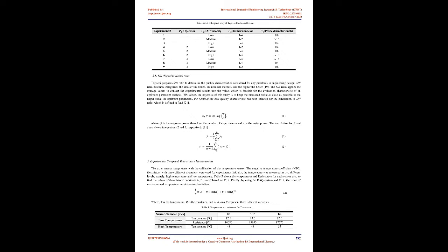It was found that process parameters such as melting temperature, packing pressure, and geometrical parameters such as gate and runner design are considered significant parameters [12 to 14]. DOE, ANOVA and TOPSIS, technique for order of preference by similarity to ideal solution, for analyzing the effect of manufacturing parameters on the final quality of injected parts were applied. The contribution of each parameter on the final result was evaluated. Many internal and external defects of the plastic parts were used to evaluate the weight of the experimental parameters. Finally, by using the DOE and its relevant tools, the optimum levels of individual parameters were determined to have fewer defects in injected parts [15].